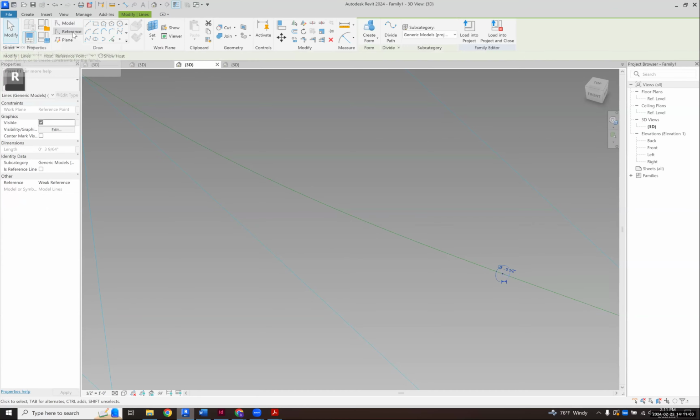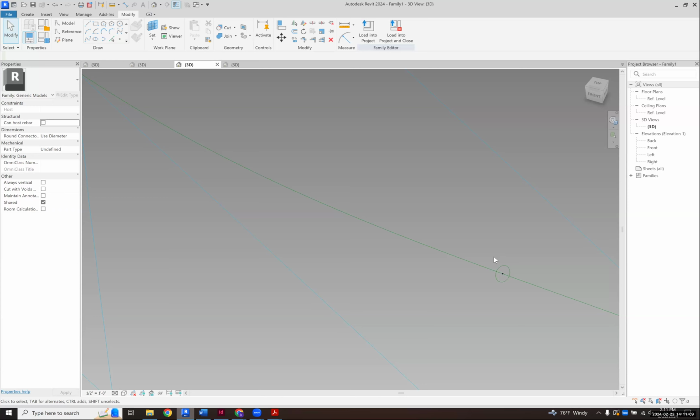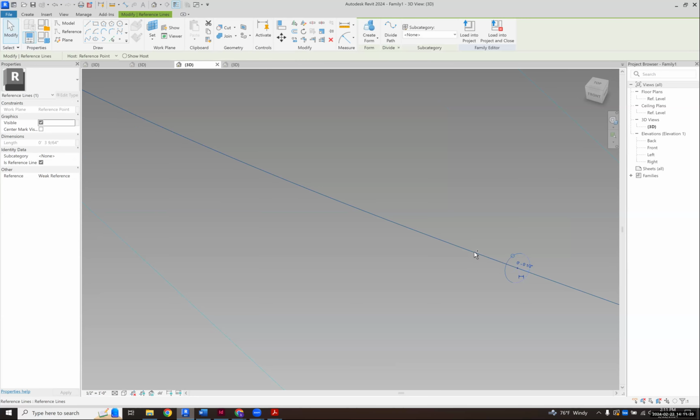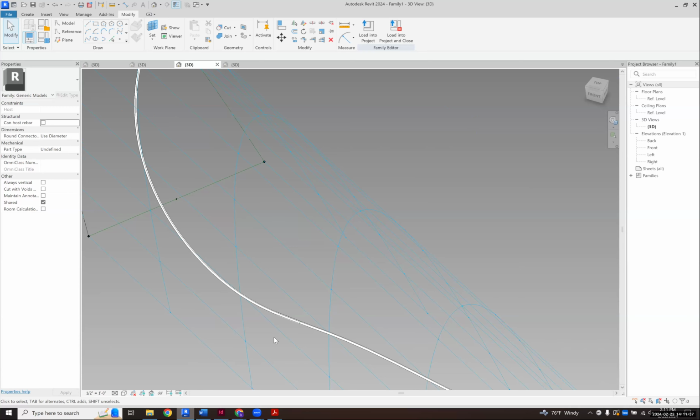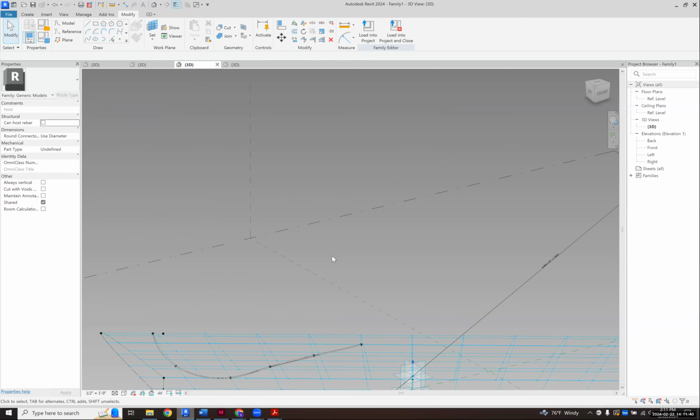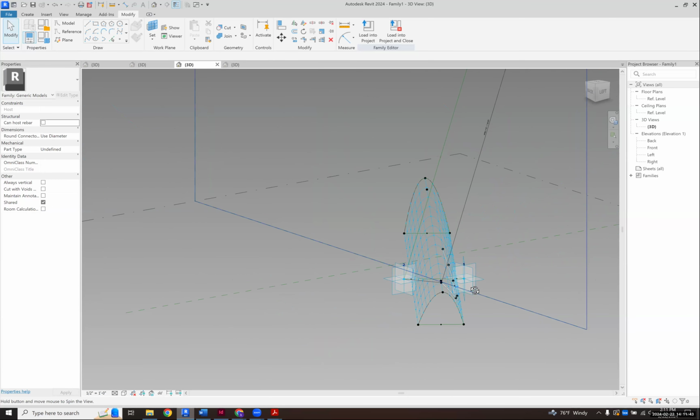I like making it a reference. There are times when you move something or have it adapt. This whole thing wants to adapt, right? That's a perfect example. If that was a normal line and then we bring this in and it changes, that wireframe wouldn't change. It would stay the exact same size because it wasn't a reference line. But now it knows it's live. So when you adjust this and it throws it into a different thing and each one's different, it'll know to adapt those to the points. I don't even need to say extrusion. It just knows, hey, I'm running a spline with a ring on it. It figures it out. So I have modeled it. It didn't matter if you modeled it. I end up drawing them real quick.